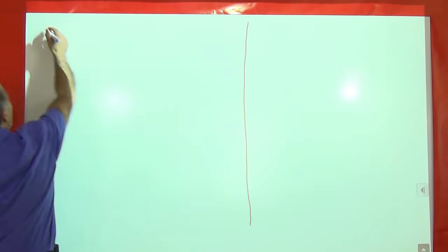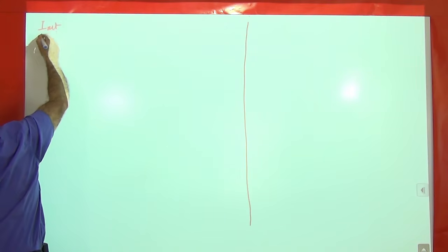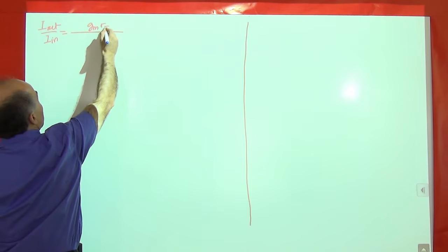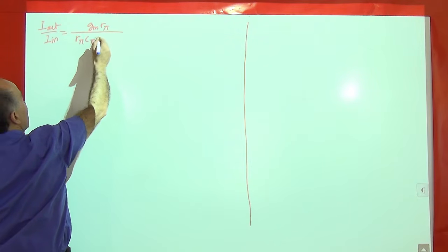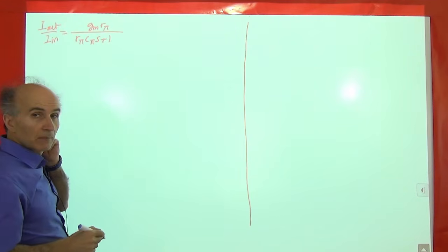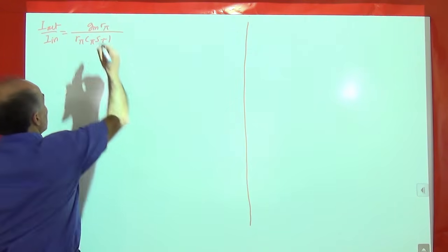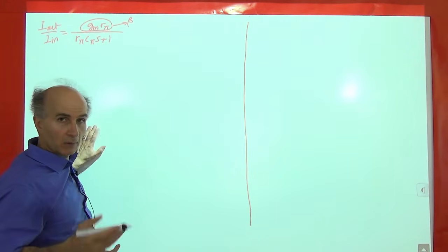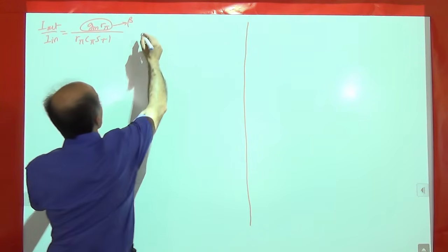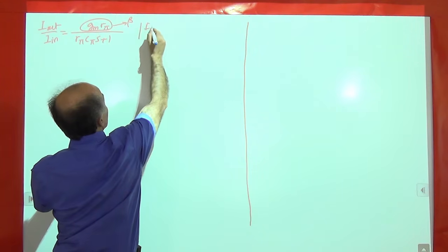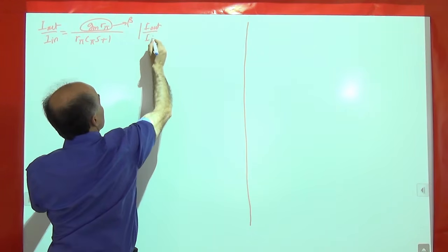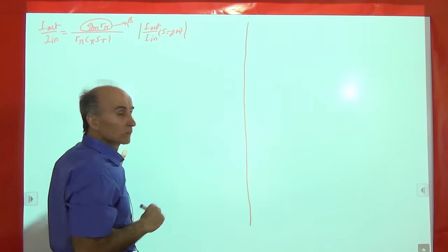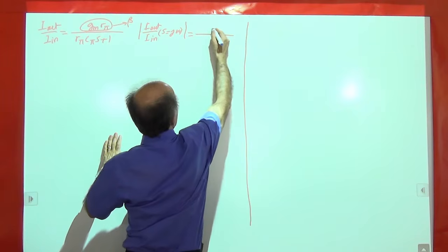Okay, so I out over I in is equal to Gm R pi over R pi C pi S plus 1. All right, okay. How much is Gm R pi? Do you remember from Electronics 1? Call that beta, right? That's the current gain, so 100 or something. Okay, so I will need to write I out over I in at S equals J omega, right, is equal to beta over that.